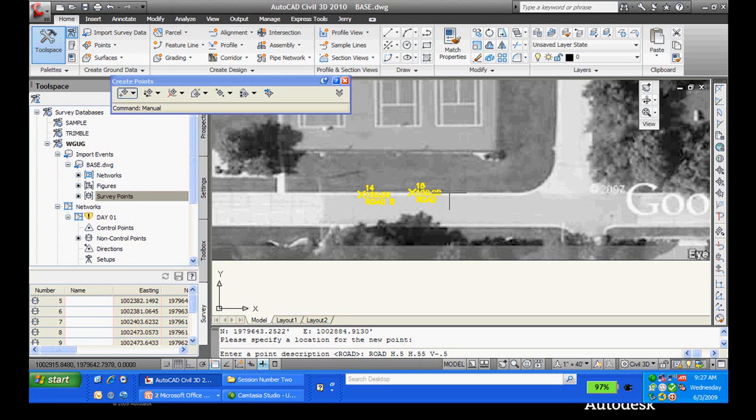Space will come out to the flag or edge of pavement. That's going to be maybe a horizontal. It'll be 1.5 foot curb and gutter. We'll say horizontal 1.5, vertical maybe negative 0.43, so that I come up from the gutter a little bit to the edge of pavement. And that's all I need.